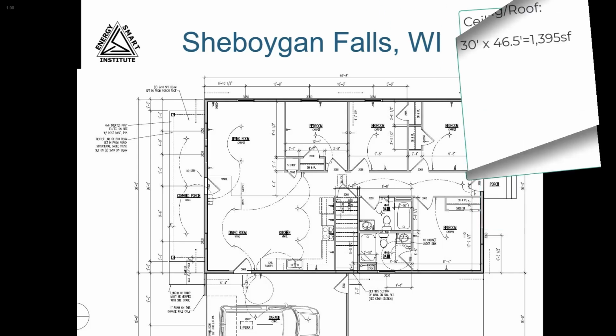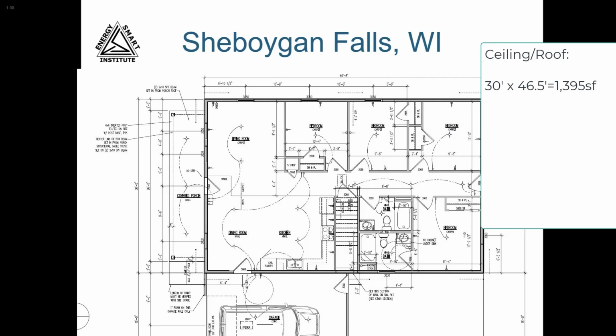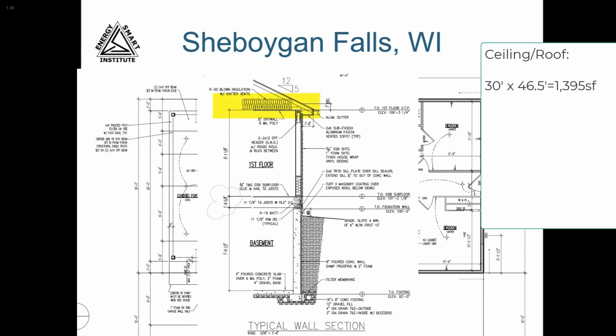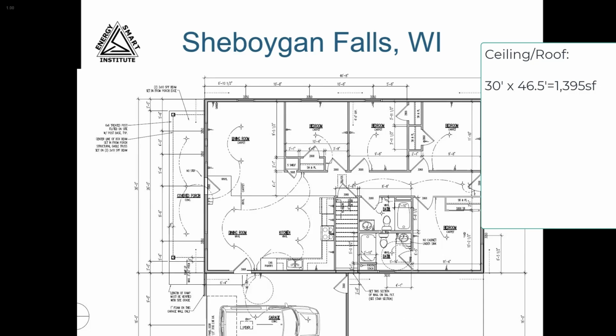While we're looking at the main floor, we can consider our ceiling area. For a sealed attic, we need to know the area of drywall ceiling, and then we will also need to calculate the exterior area of the sealed attic itself, including the roof and any gable walls that are up there. The plan shows a flat drywall ceiling, so the area is going to match the floor area. If there'd been any vaulted area, then there would be more ceiling than floor area. There will not be less ceiling area than floor area because that would mean there's a gap or a hole in the ceiling straight to the outside world.